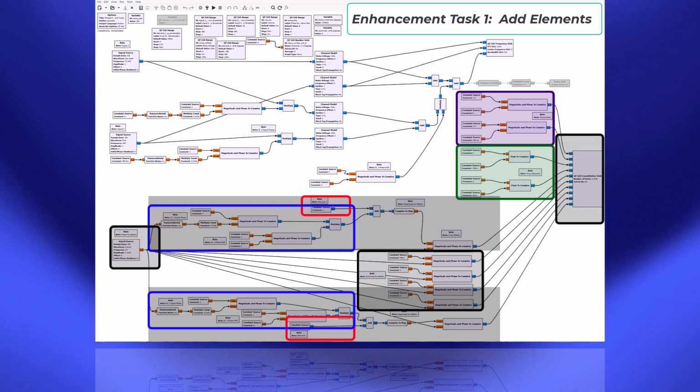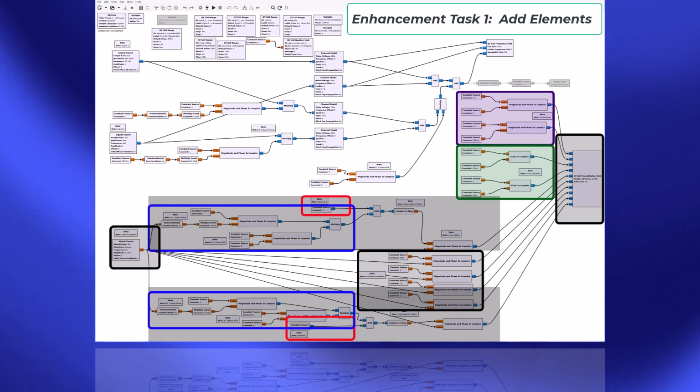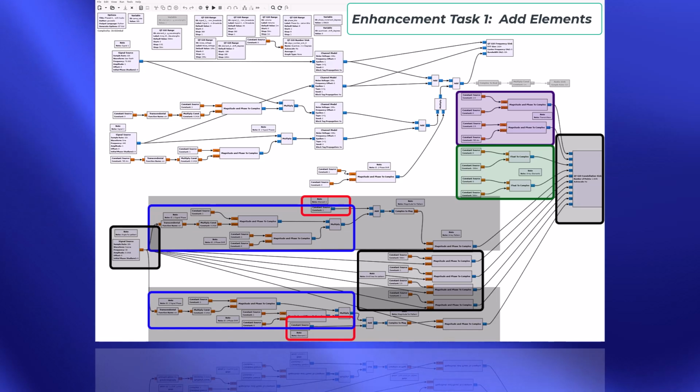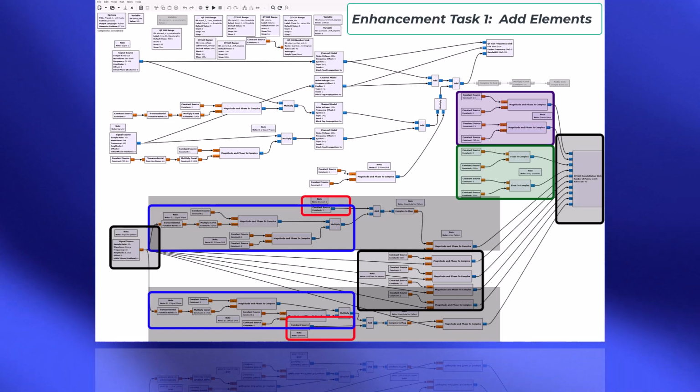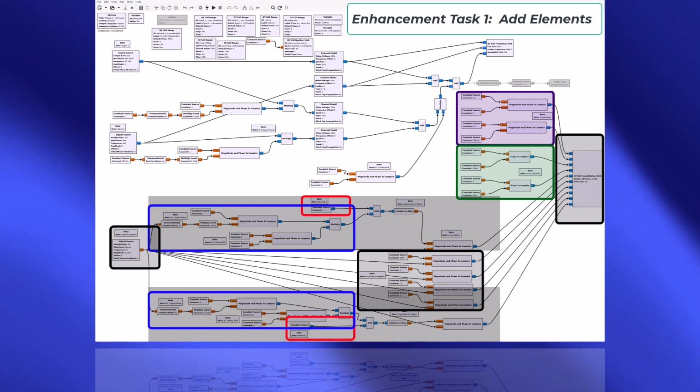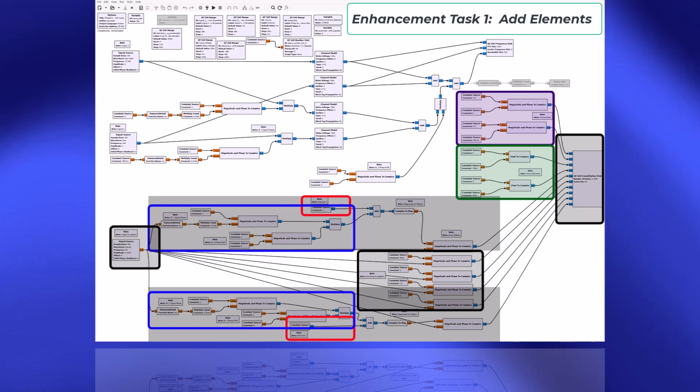For every angle, we calculate the magnitude of the array pattern and then use that as a magnitude input for our magnitude to complex block, and the phase input for that is the output of the signal generator. So for every angle, as we sweep around the 2 pi radians, we're calculating array factor at that angle, and we're inputting that as a magnitude.